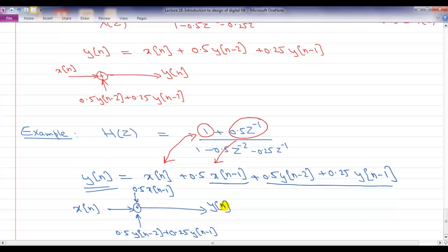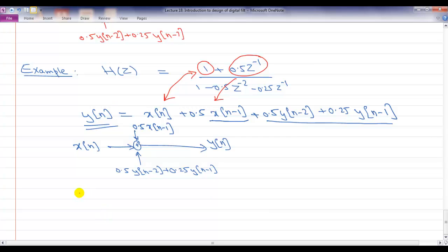Again, it's an IIR filter. You cannot implement it using the convolution sum. But since it has this special form, you can implement it using simple summation. So the question is, how do we exactly go from this polynomial to the difference equation that we obtained? And the trick to that is the same one that we did earlier. We just basically realize that H of z, by the convolution formula for the z transform, is simply Y of z over X of z.